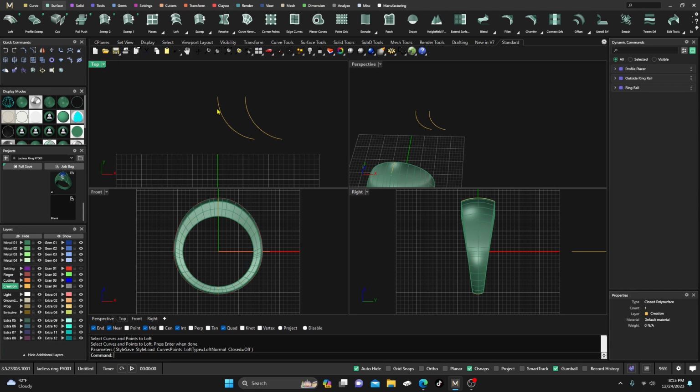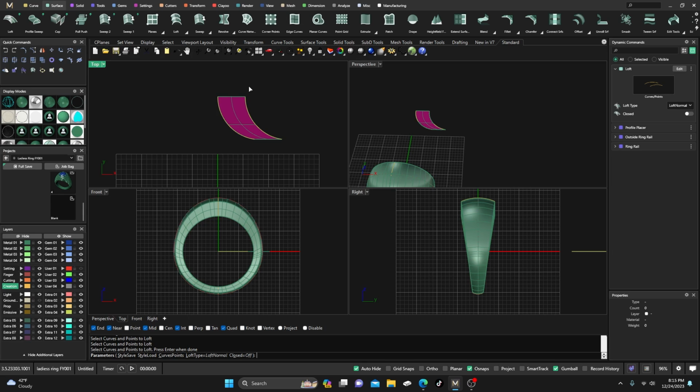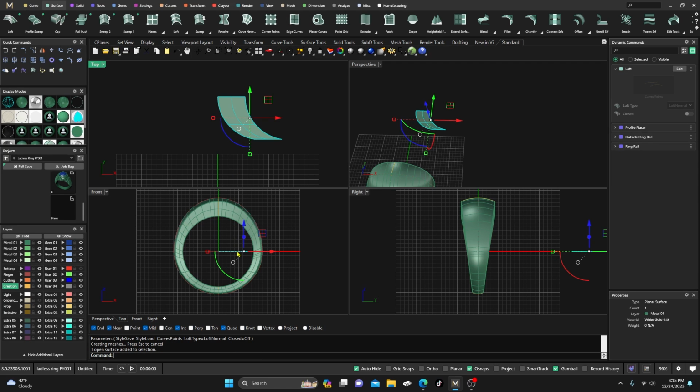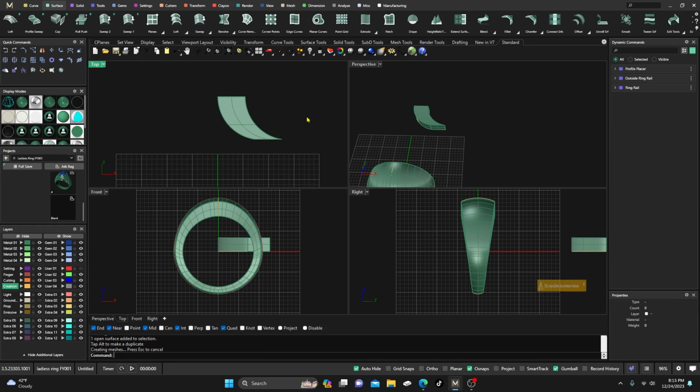Why? Probably, first of all, with Loft you want to pick the same ends, but more than likely the directions are off. So let's click on one curve, type in DIR, hit Enter. The direction's going down. Let's click on this one. I'll right click, bringing back that command, and they're going up. So we'll need to flip one of those. So we'll just flip that one. We'll hit enter. Now when I do the loft and then hit enter, there's my surface, right? Hit enter, and now I can drag that up, and I have a closed surface as well.